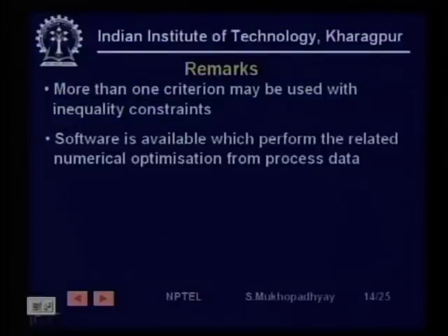In many cases your criteria may be stated in terms of inequalities. So, you actually have a feasible region in which you can operate. When you have complex processes and complex performance criteria, the calculation of the gain may require large amounts of numerical trial and error, or sophisticated optimization algorithms which search for a good value of the parameters over some feasible space. Therefore you need software, and various kinds of tuning software are actually sold by the manufacturers.